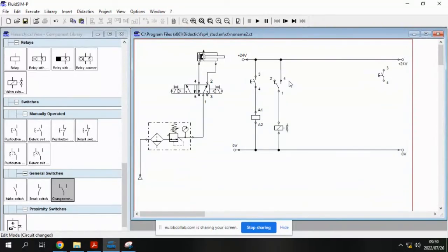You might be required to, especially for safety systems. They might come as normally closed, just like your emergency stop button. It tends to come as normally closed. You will see when we do the stop buttons very soon.